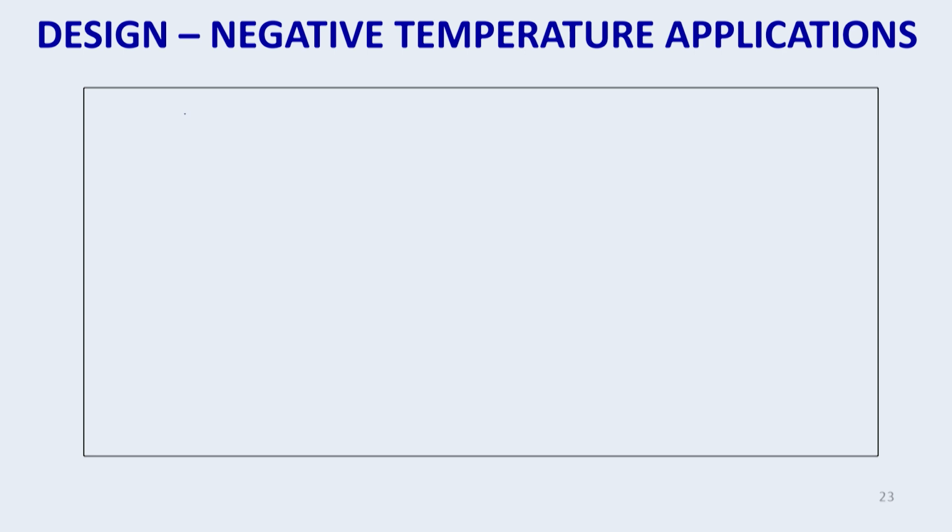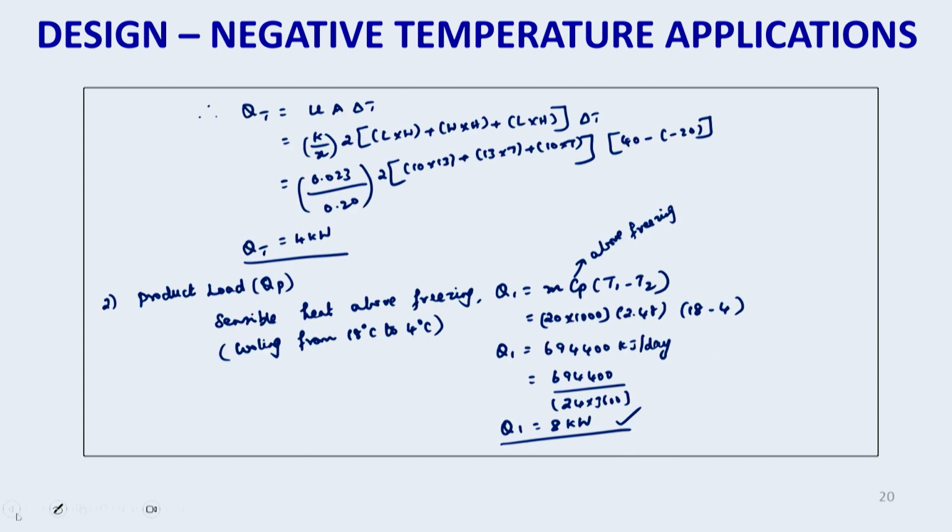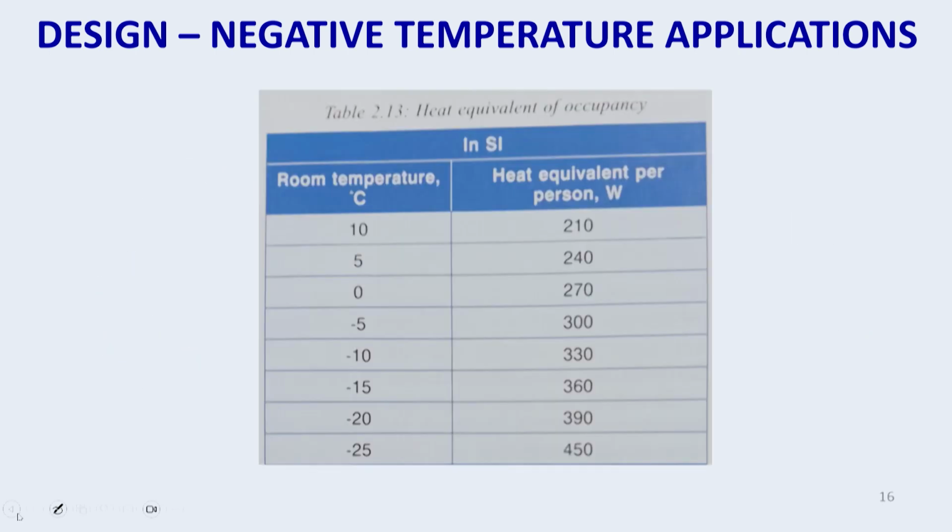Now we can calculate the infiltration load QI, which is equal to density into volumetric flow rate into enthalpy difference. For this problem, the enthalpies of air are given.